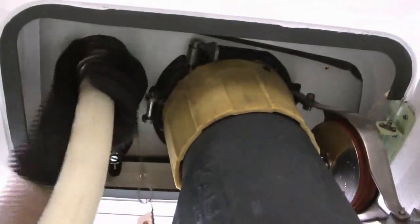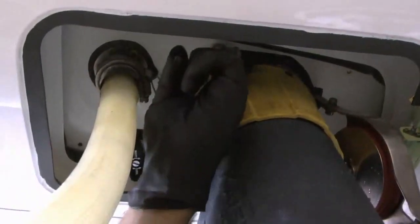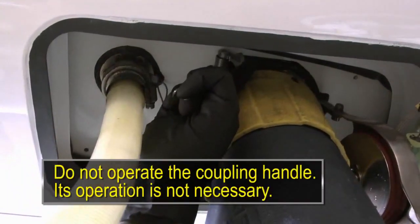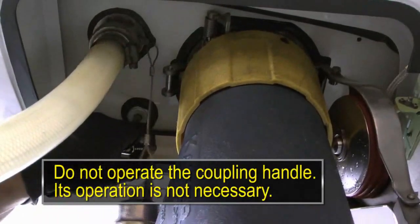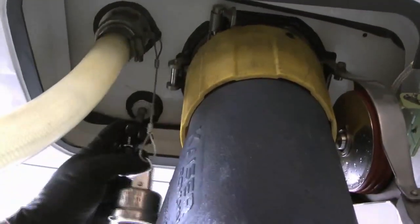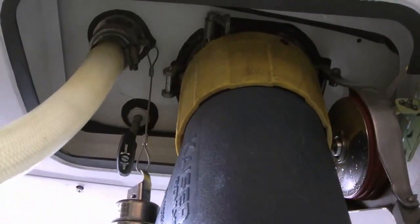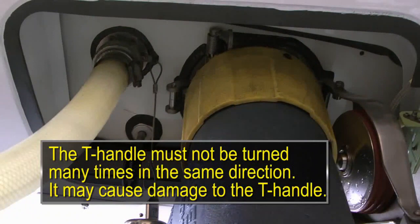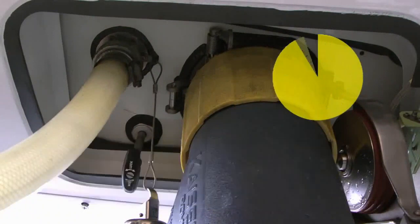Connect the lavatory filling coupling of the RTS rinse valve and push the lever of the RTS service panel drain valve to open its internal flapper valve. Pull the T-handle out and turn it to lock the RTS waste drain valve in the open position. Continue the waste tank drainage until the waste flow stops. Flush the waste tank with water through the RTS rinse valve for about 3 minutes.